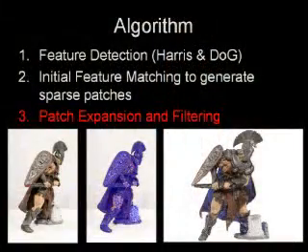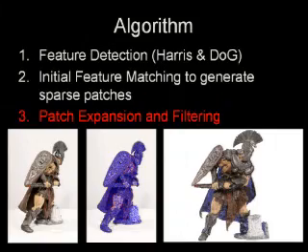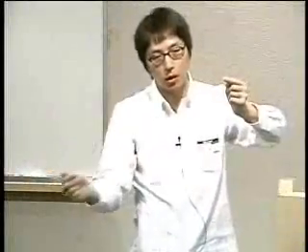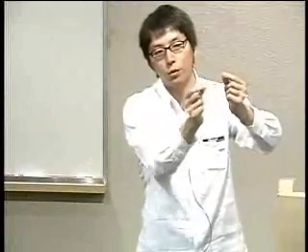I see. So in the snapping framework, we need a mesh model, and what we do is, for each vertex, we have the estimated normal from the mesh. We find the reconstructed patch which is along the normal, so you know how much this vertex should be moved inward or outward. We move this vertex little by little with some regularization. So it's okay if there are no patches reconstructed, some hole. It's just going to be snapped with only regularization working, so you get a smooth surface. It's a way to add more information, filling holes.